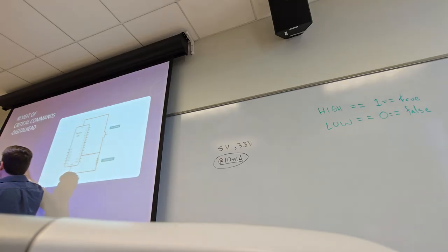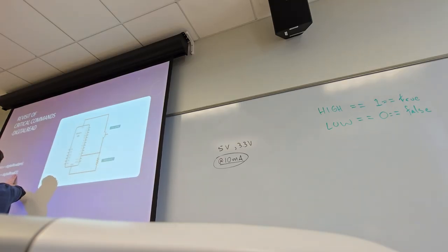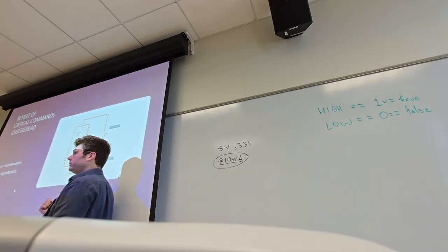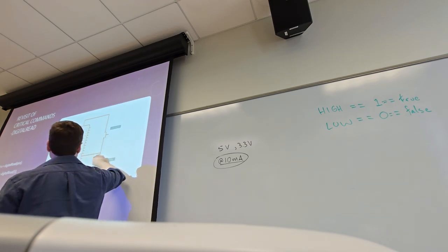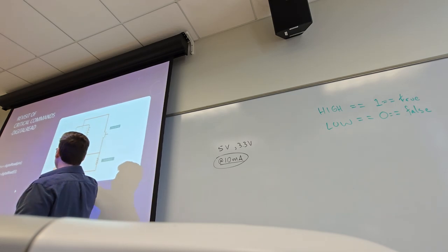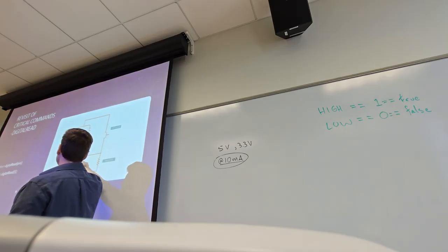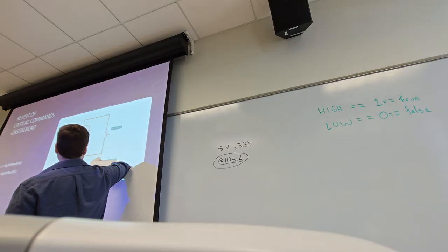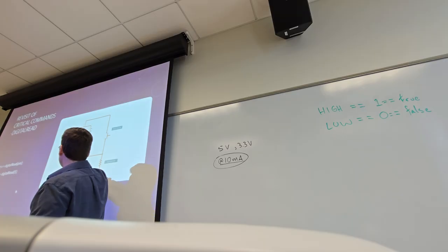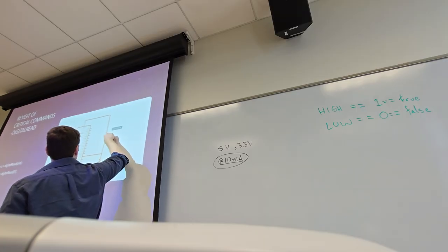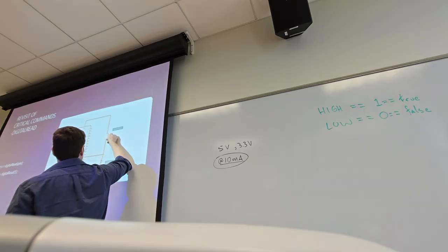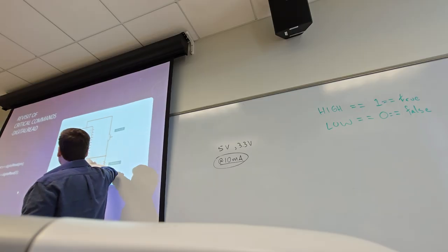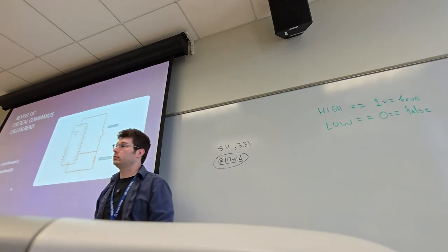So we wouldn't have had to declare our pin, which is 5 in this case, as input pull-up because we have an external pull-down. We would just set it as input. But doing that, we can read the state on pin 2 in this case. I should have put digitalRead 2 instead of digitalRead 5 over there, but we would be reading the state on 2. When this button is not pushed, the state on 2 is ground, because we're going to ground. But when we close the button, we will see high, because 5 volts will come through here, and then we will see high volts on our 2.